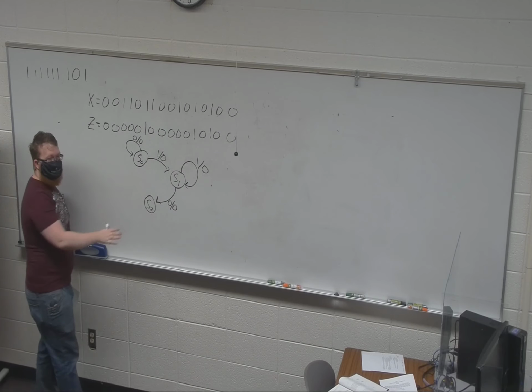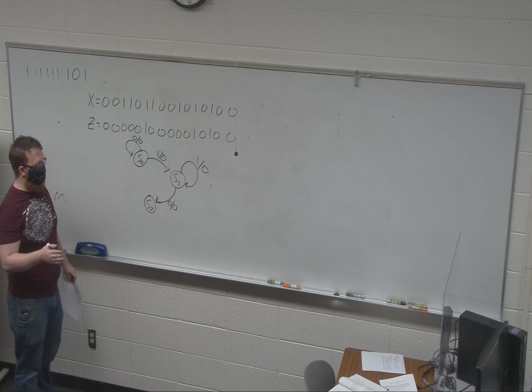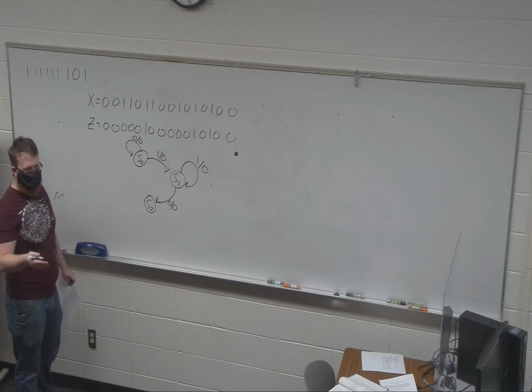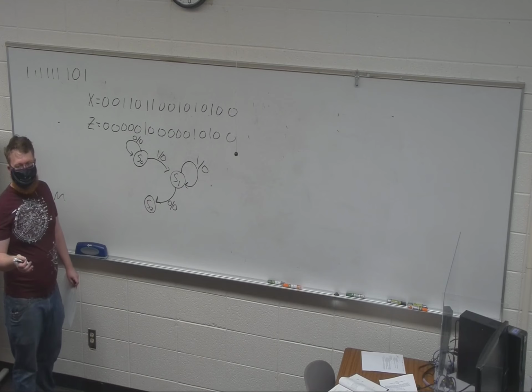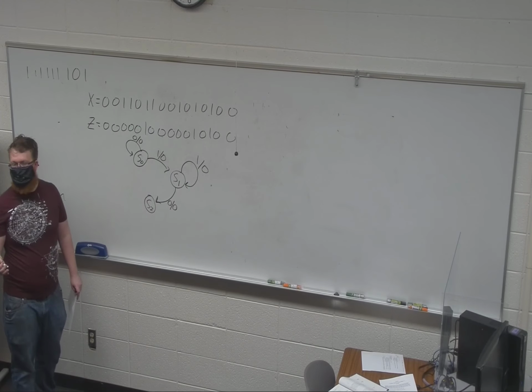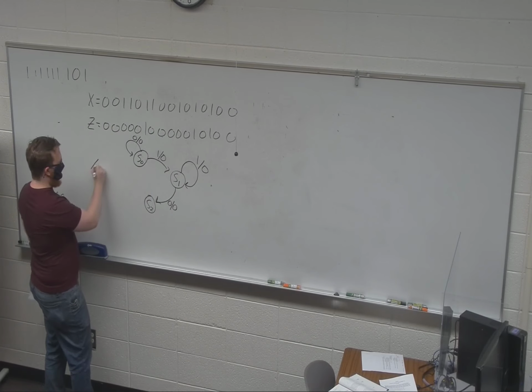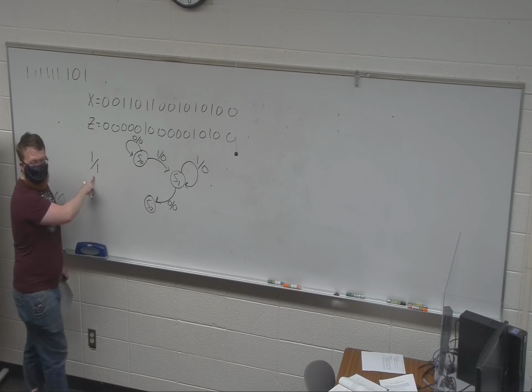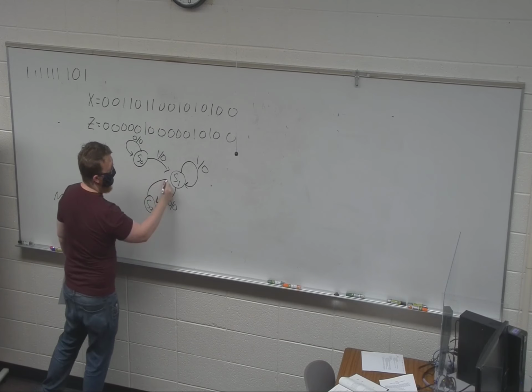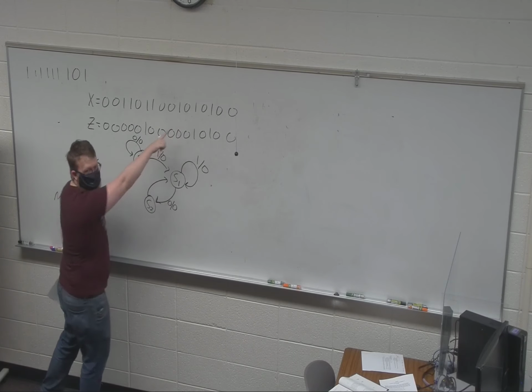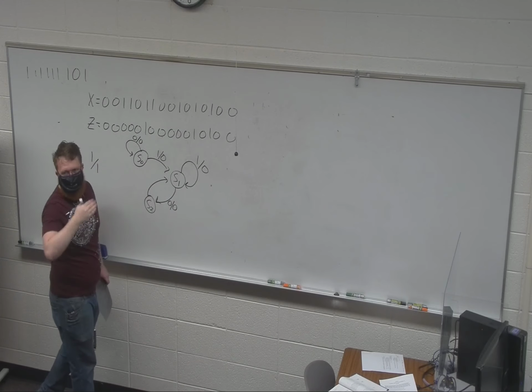So S2, similarly, it has two different things that it can see. What happens if it sees a 1? It's going to give you a something over 1, right? So it sees a 1, it's going to give a 1. Where does the arrow go? Yes, exactly. It goes back to here because that could be the next 101.